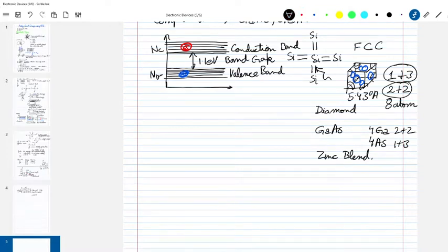So we know that electrons and holes are generated in pairs. This can be done by raising the temperature most easily, or it can be done by stress, or by a photon, right? So anyway, I can supply energy. Most prominent is temperature. Now these electron-hole pairs which are generated because of temperature are known as intrinsic carriers.